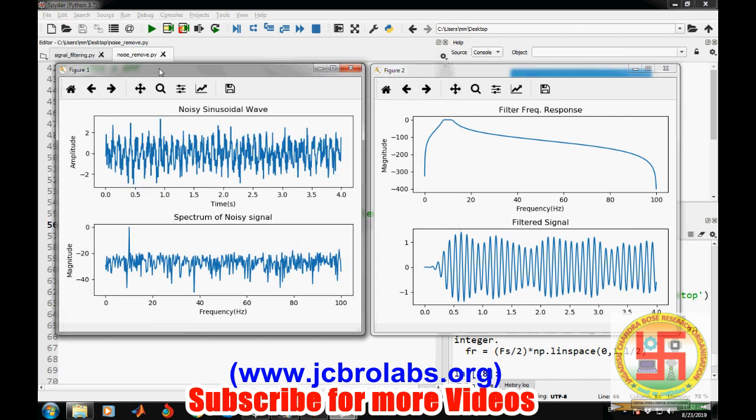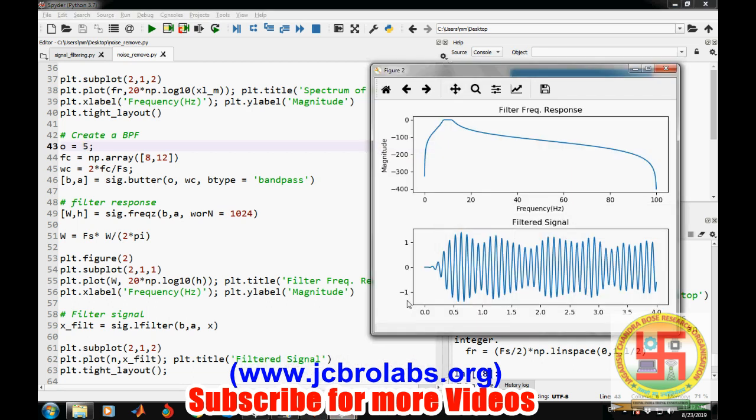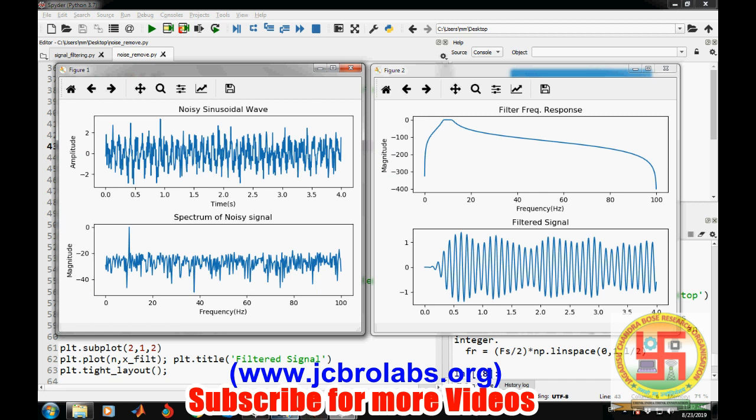Obviously the high cutoff frequencies are not that efficient, so we are getting the frequency of the filter quite clearly, but it is very observable from the amplitude that there is a change in the amplitude, or we are getting fluctuations in the amplitude. So this is how we filter our signal, right? There are several ways to change this. Also, one thing you should notice is that at the starting part there is no response. This is known as the filter delay, and that depends upon the number of samples we are using in the filtering operation.